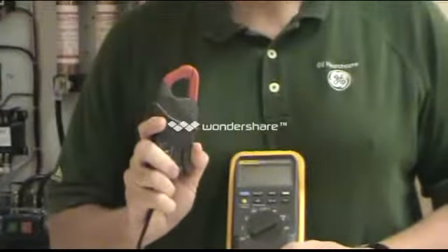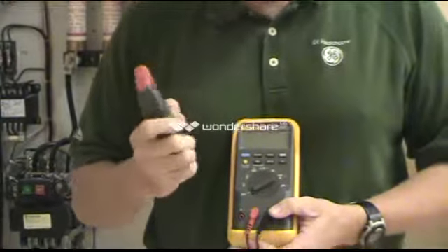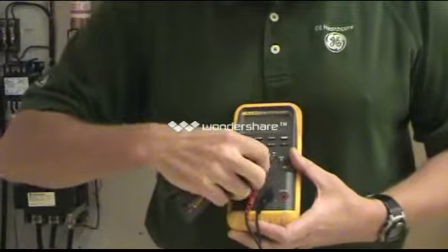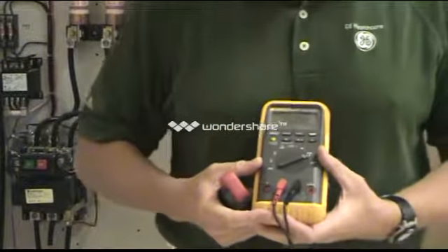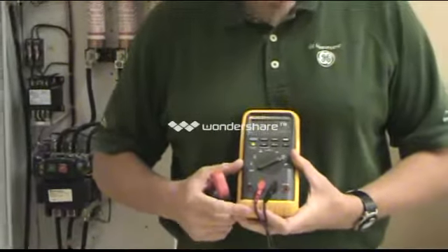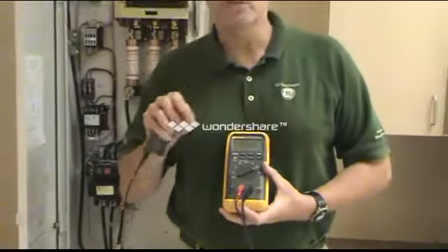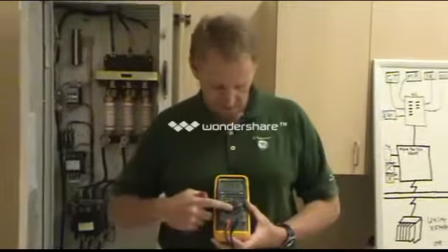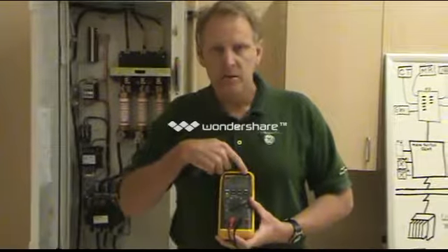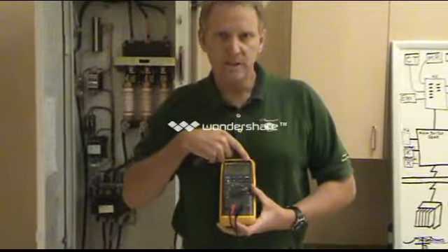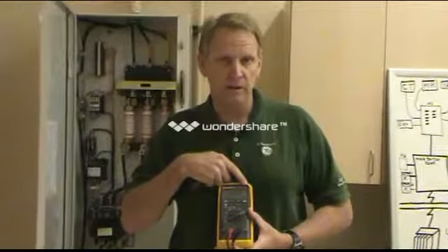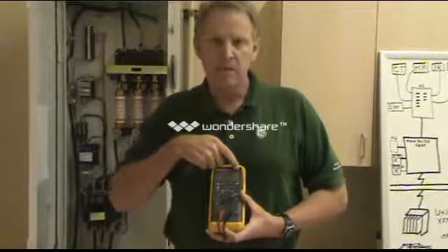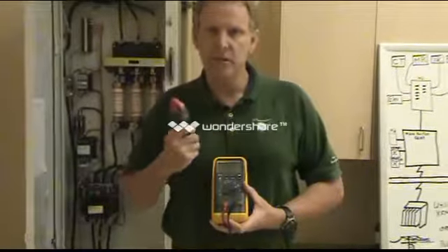This guy is a 1,000 to 1 multiplier, so any readings that we get, we have to multiply by 1,000, and we have to be on AC. So our phase currents, if you read the documentation, big red boxes on there say put it on the milliamp scale and put it on AC. Some of the newer Fluke models will actually default to AC, but most of them are going to default to DC. In order to change it, you have to hit the blue button, and check and make sure it says AC up there. If it is, you're good to go.